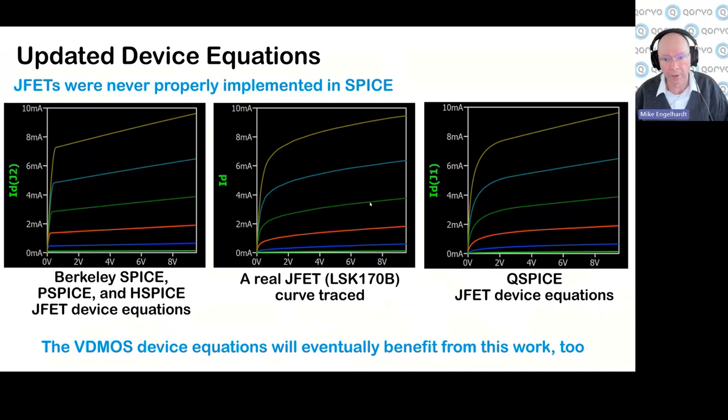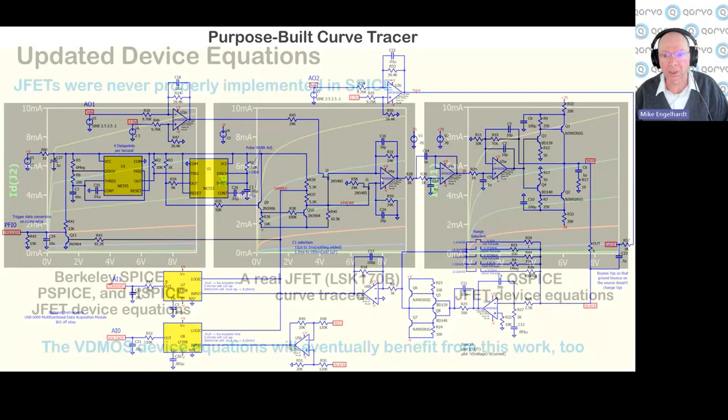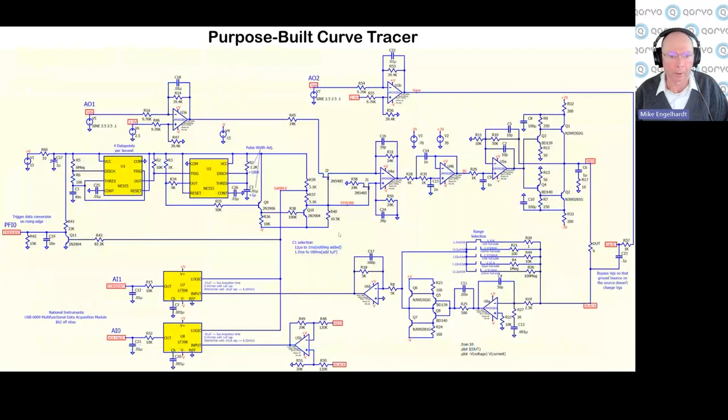So anyway, to measure this stuff, this was the setup I used. There's a time base here. And the choice of components was that this is all through hole, because I have no way of dealing with surface mount. I just don't have any gear for soldering anything surface mount. So it's all through hole stuff. So this is the circuit I use. I have a time base, and then I have to level translate. I have to tell the DAC when to fire the convert.